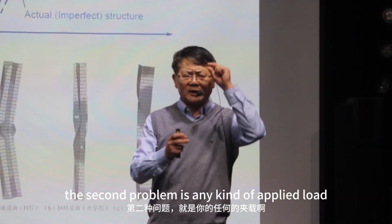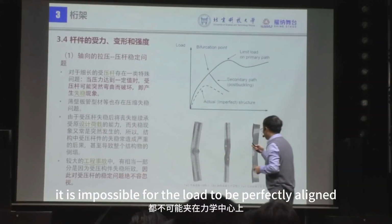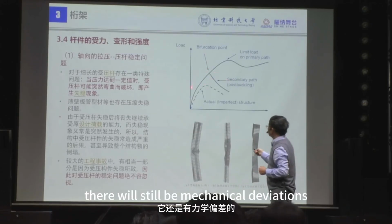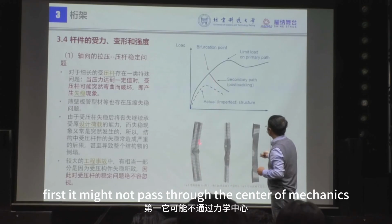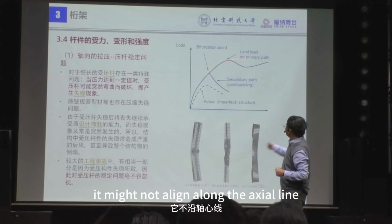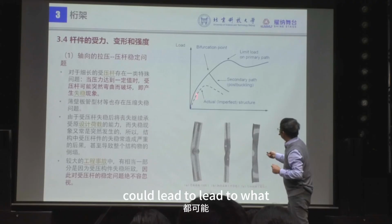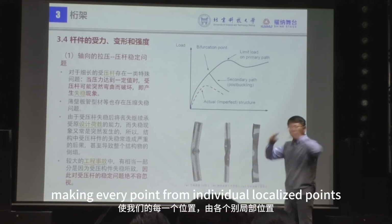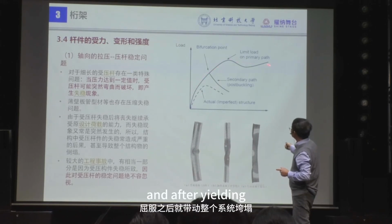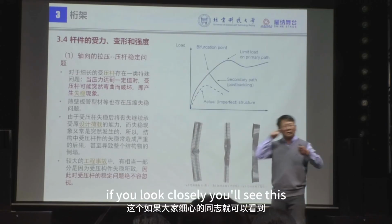The second problem is any kind of applied load. Even with an ideal applied load, it is impossible for the load to be perfectly aligned with the center of mechanics. There will still be mechanical deviations. First, it might not pass through the center of mechanics. Second, if it does pass through, it might not align along the axial line. So these issues all could lead to what? Individual localized points first reaching the yield point, and after yielding, triggering the collapse of the entire system.